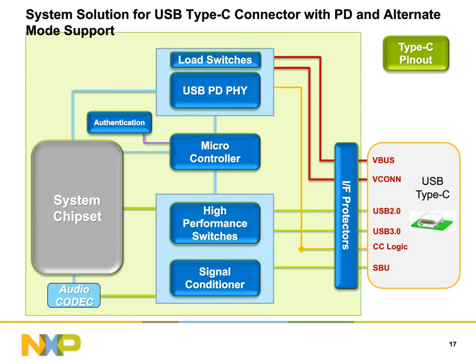So for instance, it can allow the Type-C connector to authenticate the power supply that is connected on the other side, or the cable, or the accessories that are connected on the other side before it starts accepting any charge or data transfer, as an added security feature to make sure that you are protecting your design. So authentication is also a very interesting technology that can complement the Type-C design very well and make your system very secure. So all the blue blocks that you see here are the key pieces in the Type-C design, and NXP offers solutions for all these blue blocks.